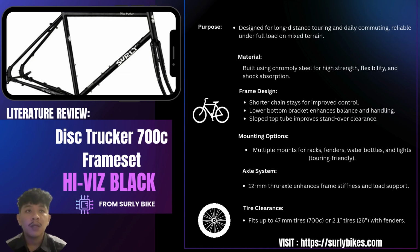For the mounting options, there are multiple mounts for racks, fenders, water bottles, and lights, which is touring friendly. For the axle system, 12 mm through axles enhance frame stiffness and load support. For the tire clearance, it fits up to 47 mm tires for this frame, or 2.1 inch tires, which is 26 inches with fenders.